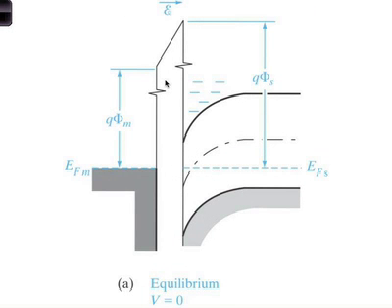Okay, first of all, phi ms is basically this, right? Typically, in a typical situation, you have a metal oxide semiconductor. This is something you've seen before. When the metal work function is smaller than the semiconductor work function, the bands have to bend because the Fermi level, there's no current flowing, so the Fermi level here has to match.